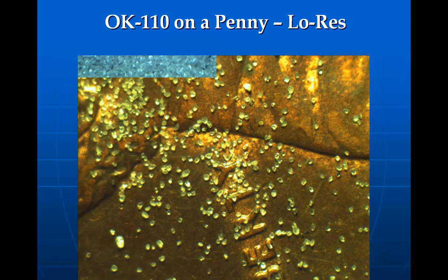Now, this isn't meant to brag. I just want you to understand something. We caught 98% of the 60 micron particles and above in the field for an ETV test in Griffin, which a lot of jurisdictions don't think is good enough. But this can give you an idea of the size of the particles you're dealing with. By the way, most separators can do that without a ton of trouble.